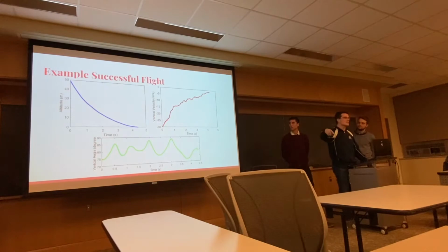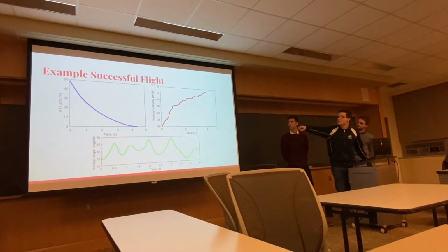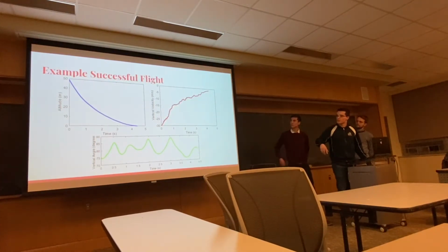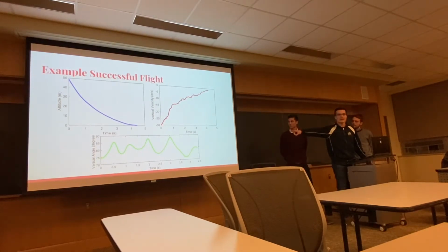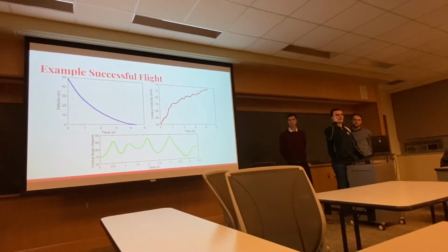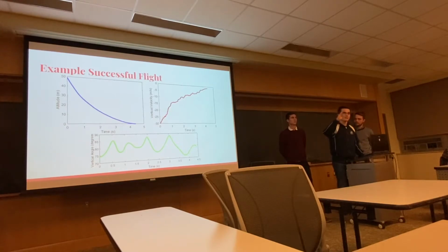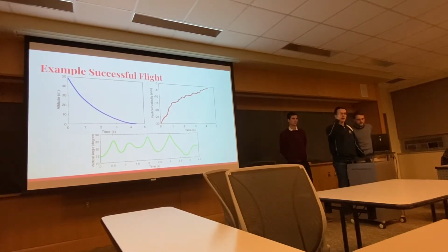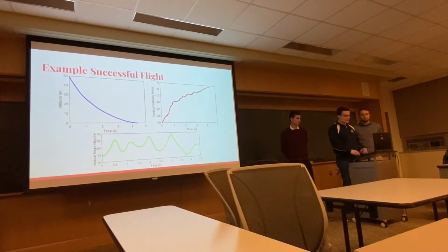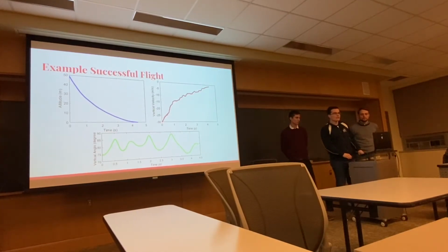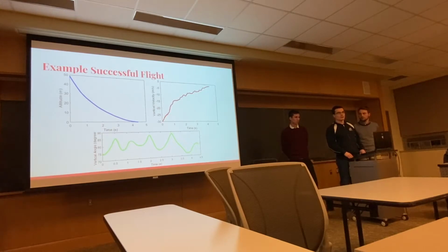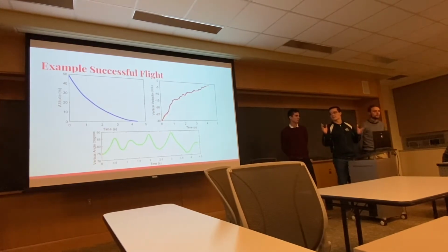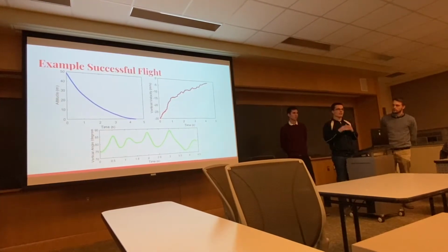The velocity starts at negative 30 meters per second, and you see it gradually goes to about 0, and then this green down here is the vertical angle. So it started at 75 degrees, so a pretty good tilt on it, and then it kind of came back and started oscillating around the middle. So that's what we wanted to do. We're not using angular velocity in our state definition either, so it has no sense of momentum, so it can't do better than just oscillate around the center.